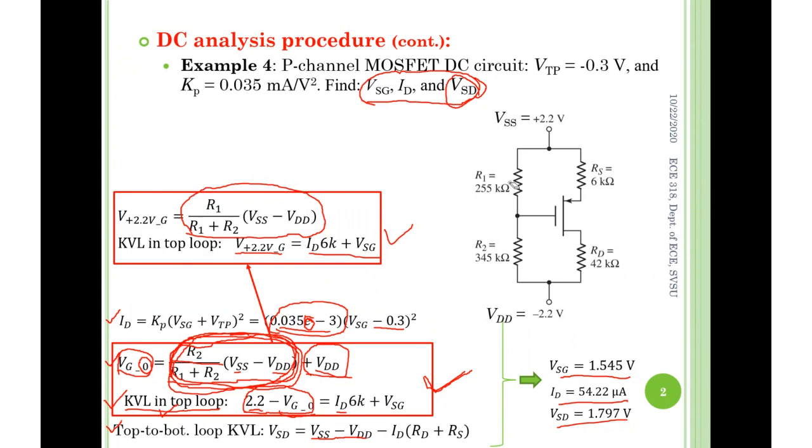across the resistor involved in that VSG loop, rather than the voltage across the other resistor R2. No, that voltage across R2 is useless. We don't need that. We need the voltage across R1 here, because that voltage is part of the KVL in this loop.